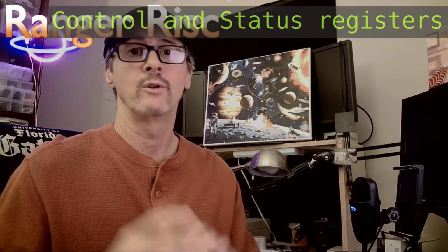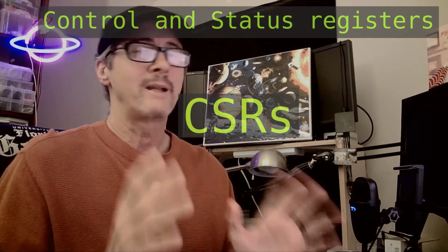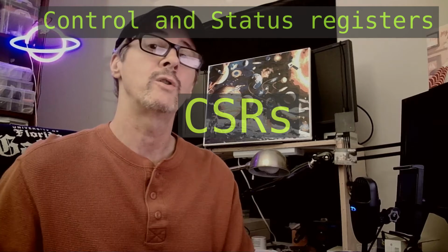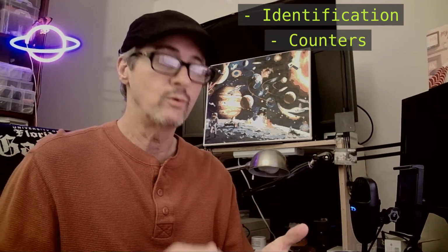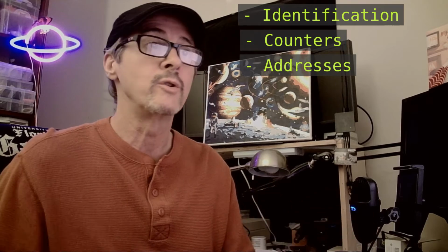In this episode, we travel the outskirts of the world of control and status registers, or CSRs. Why only the outskirts? Because CSRs encompass a huge range of capabilities and functionalities. For example, identification, such as the machine ID, counters like cycles and retired instructions, addresses like trap vectors, mode bits